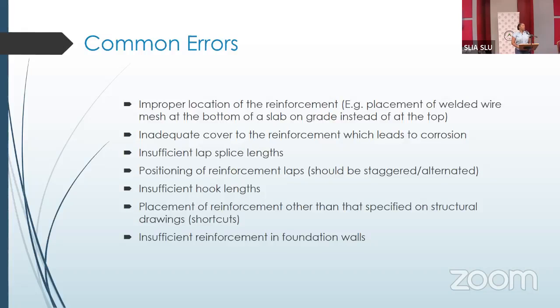Positioning your reinforcement, especially when we have those lap splices. Whenever we have to splice the reinforcement, it means that we need a length that is much longer than the actual length of steel. The length of steel is generally, I think, 19 feet, if I recall correctly. Some people will tell me it's 20 feet, but I know it's 19 feet. They make them 20 now, so I'm from the old school chapter where it was 19 feet.